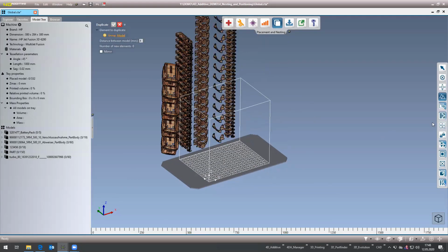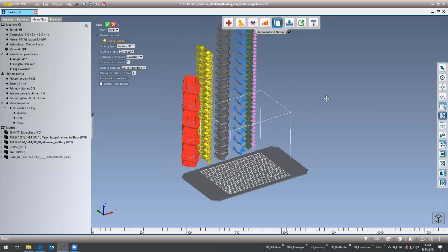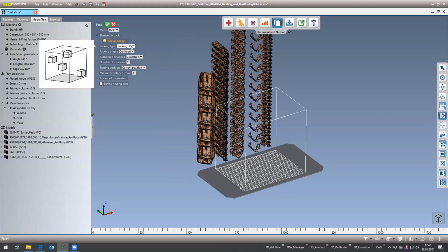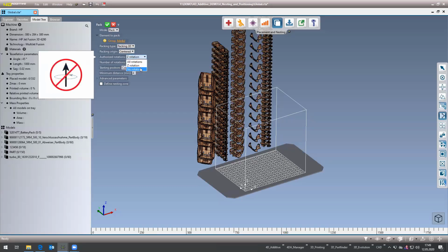And now what I will set up is the nesting algorithm. So we can, of course, I will show the nesting in 3D, but it also works in 2D actually for metal printing, for example. Just fill up the whole platform, not going up into Z height. So I would choose 3D nesting. Then where to start, for example, in the middle of the machine. Then you can set up which kind of rotations are allowed for the parts.